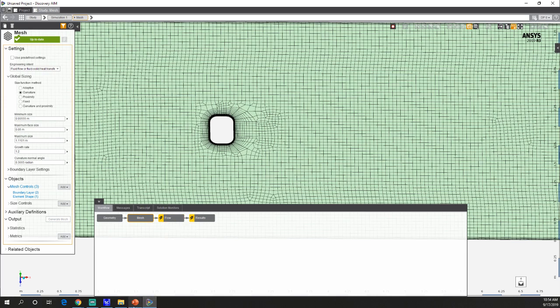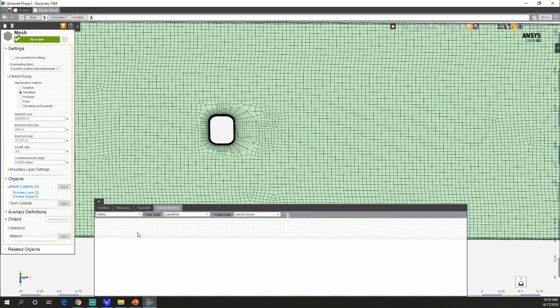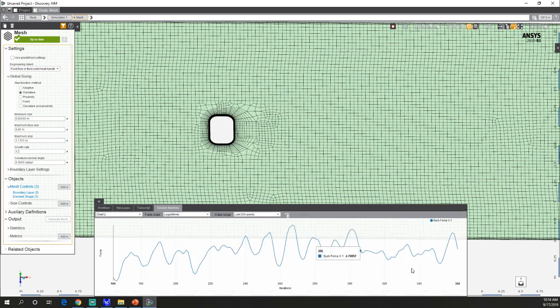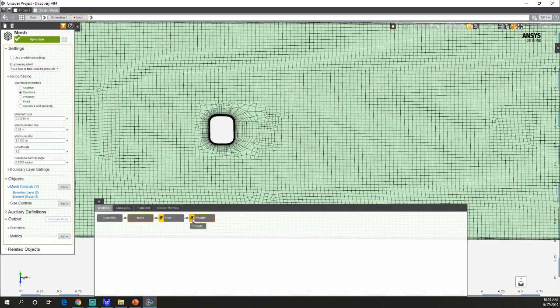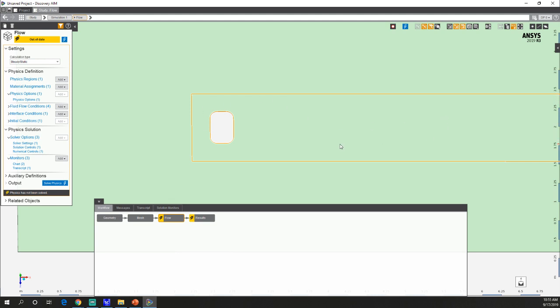And finally, doing a transient simulation so you get the transient behavior for this type of blunt body model is really important because in testing, you're never going to get perfectly symmetric flow in your system. So doing a transient simulation gives an idea of what you would actually see in a wind tunnel versus idealized simulation results.